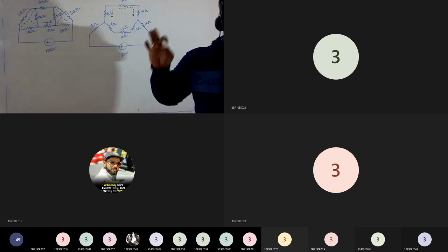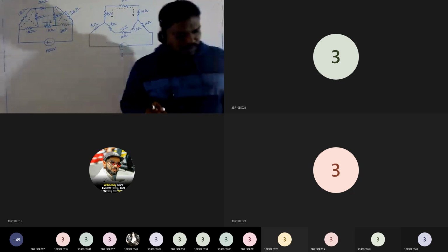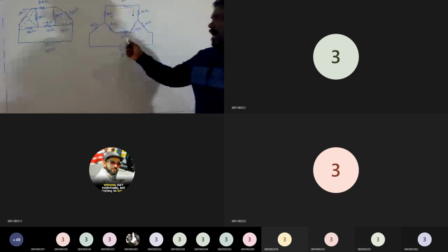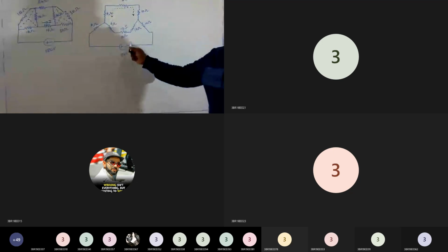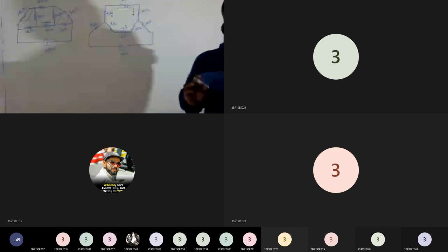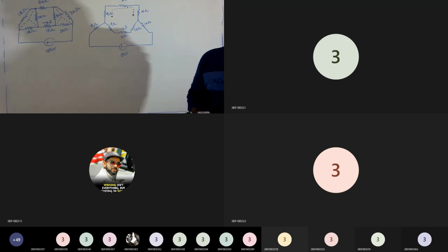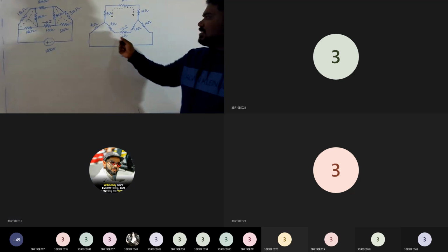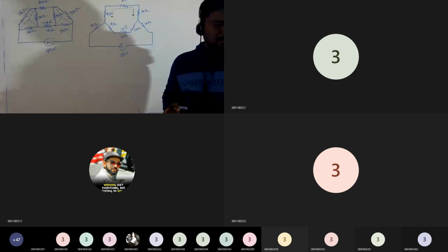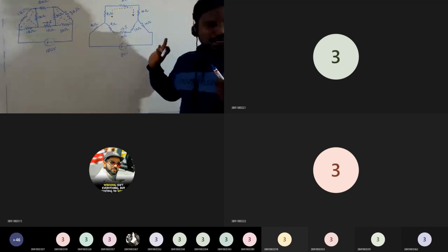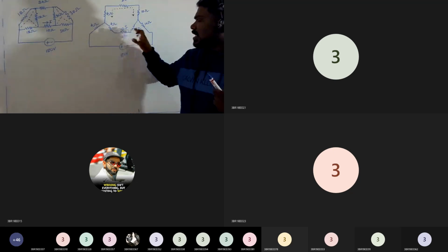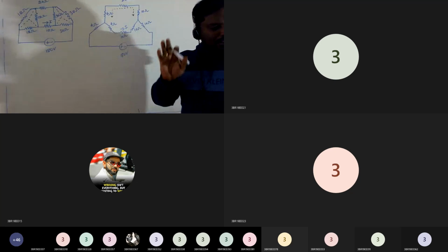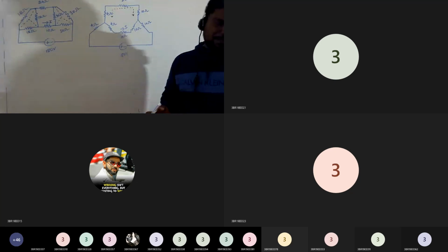I explained to you even while learning the concept of source transformation that wherever they ask for current through an element or voltage across an element, that particular resistance must not be considered for simplification. I have repeated this statement many times. So I don't consider these resistors for simplification. But I know that even if I consider them, there will be no effect on the current because all three resistors are in series. In series connection, current remains the same.